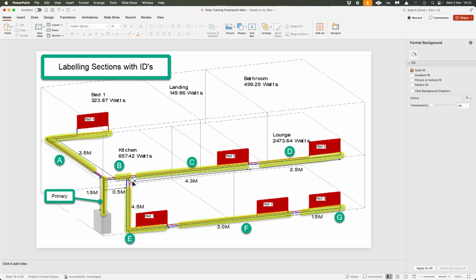I put down here from this T-piece, I put 22 millimeter down to the edge of that radiator because we've got quite a high heat loss here. But there was 22 millimeters there, or we could say that it wasn't there, and the bit of floor or the bit of ceiling might have needed to be taken down there and joined into that primary flow and return to drop down. But in this case, it was there, we're saying. But then from there, I dropped it down to 15 millimeter all the way down to this end section.